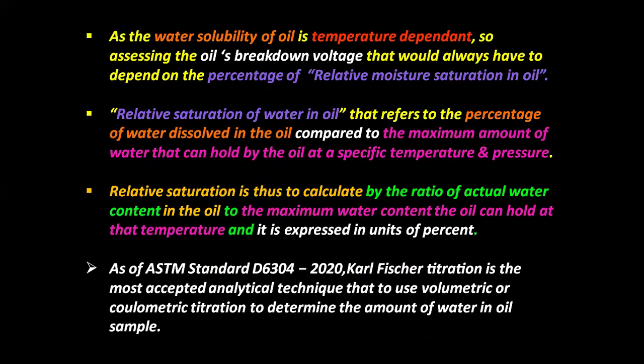Relative saturation of water in oil refers to the percentage of water dissolved in the oil compared to the maximum amount of water that can be held by the oil at a specific temperature and pressure. Relative saturation is thus calculated by the ratio of actual water content in the oil to the maximum water content the oil can hold at that temperature, and it is expressed in units of percent.